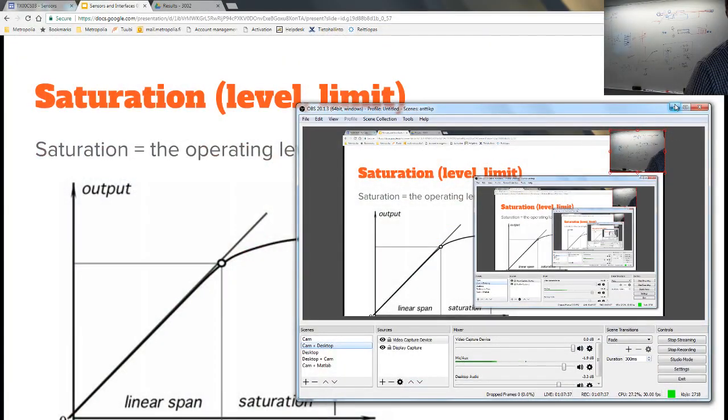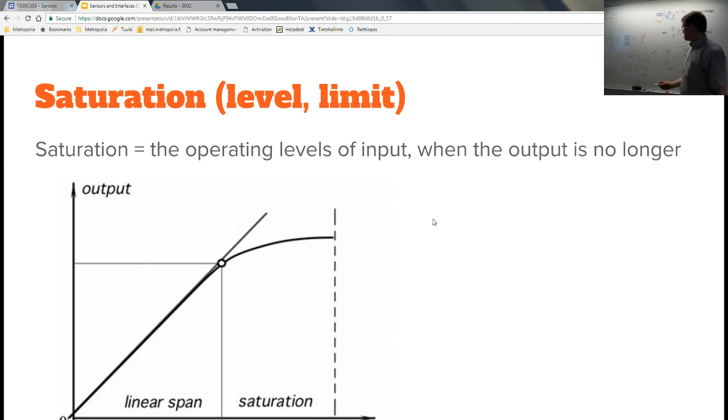Exactly like in this picture. So it starts saturating. Normally, that's where you stop measuring. But if you really have to have very wide dynamic range, more than 100 dB, so if you want to measure a very, very small amount of light with the same experiment, you are using 10 to the, let's see, 100 dB is 10 to the 5. 10 to 5 more light. And still have measurements, so not just guesses, not just nice pictures.